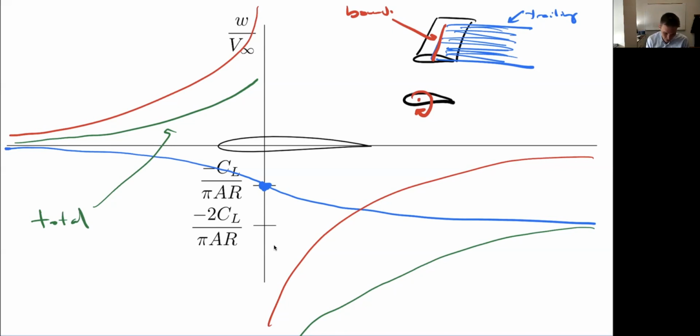And here's why. Let's imagine a generic case. Here's an airfoil, and it's got a bunch of bound vorticity. We could lump it all up into one bound vortex, but we could also think about many bound vortices, or you think about a swept wing where the bound vortex has different segments. Let me just consider any 2 arbitrary components of these bound vortices.